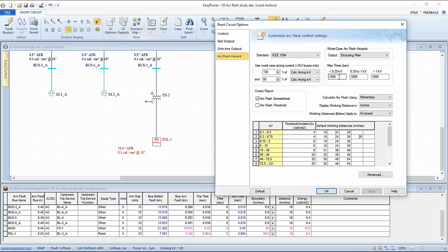Now this is one of the recommendations, and we actually have an apps note out on this for low voltage applications of the model. The short version of the story is, during testing, IEEE had a difficult time sustaining an arc below 240 volts.